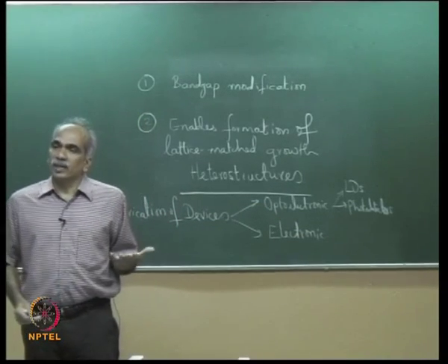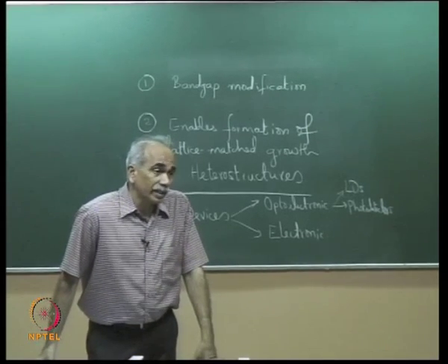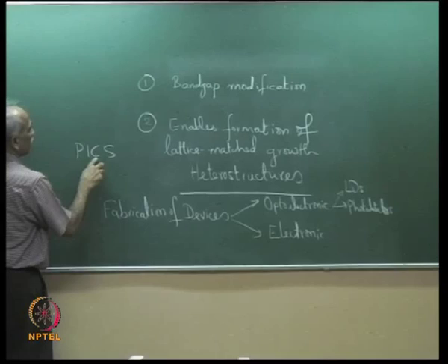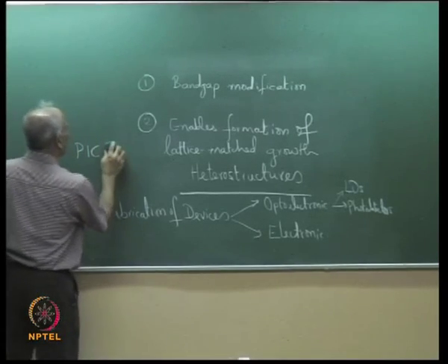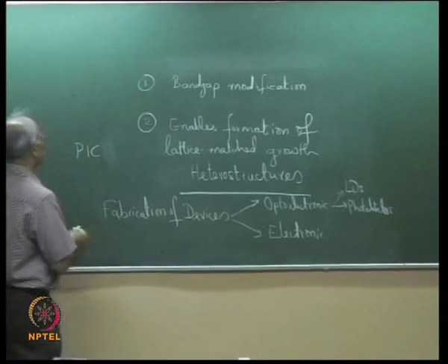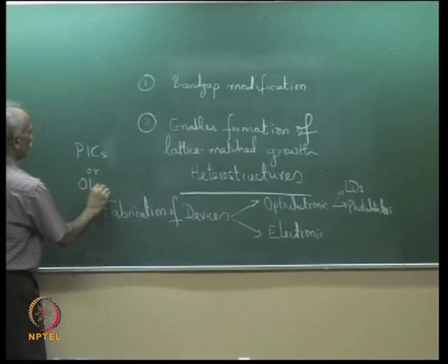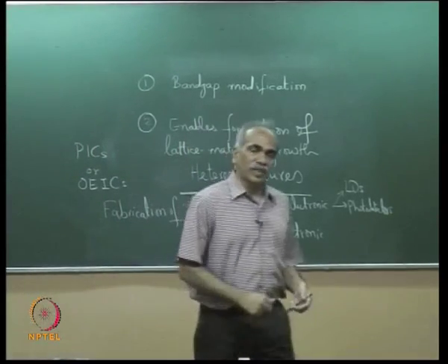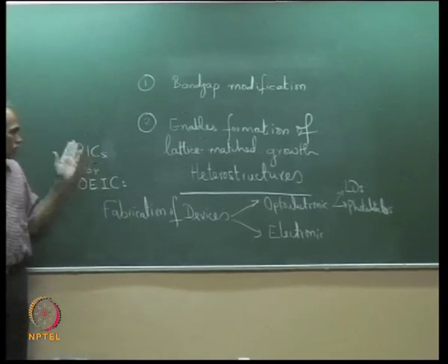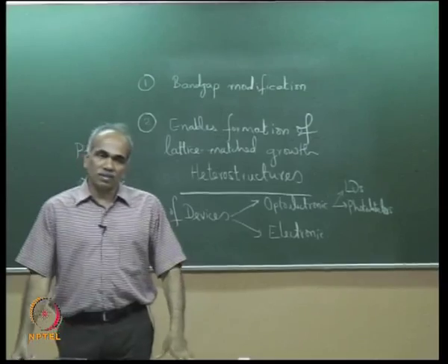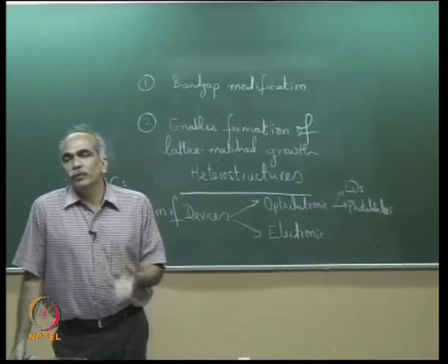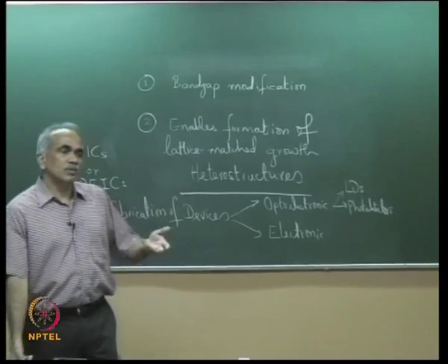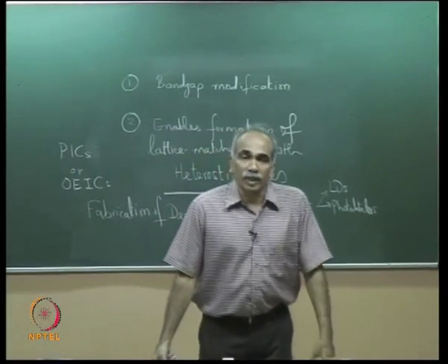Typically an optoelectronic chip, now called a PIC, photonic integrated circuit, earlier also called an OEIC, optoelectronic integrated circuit, like the ICs we are familiar with in electronics, has generally very few components, 3, 4, 5, 6, 8, because each component's dimensions are typically tens of microns to hundreds of microns.